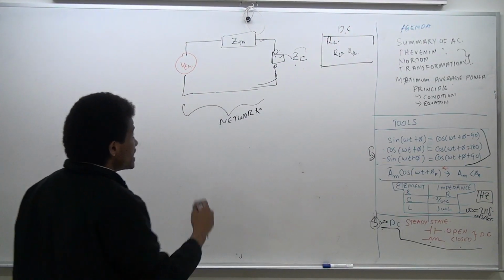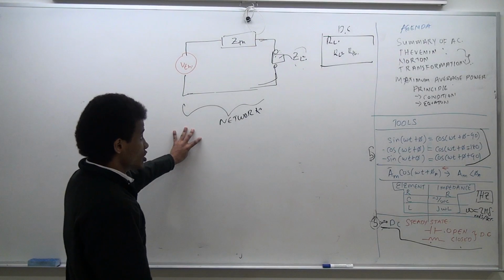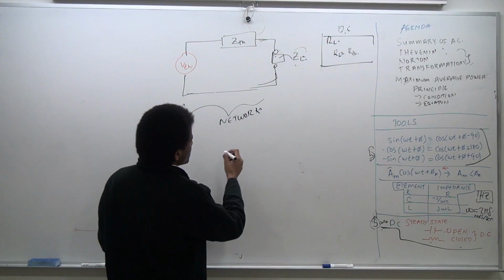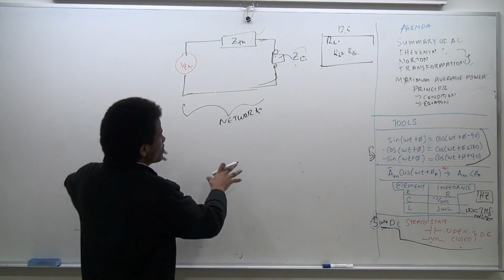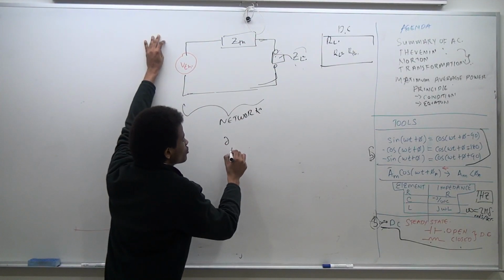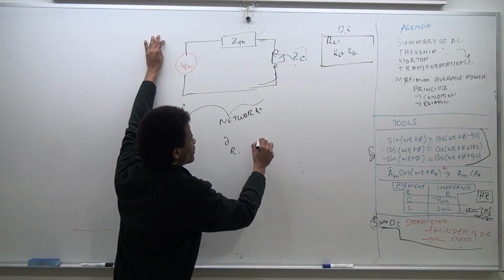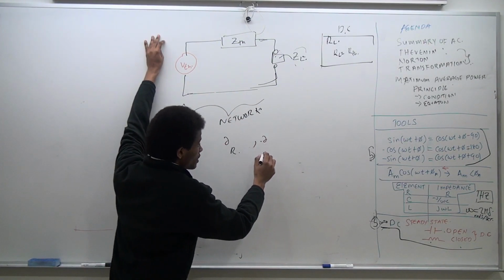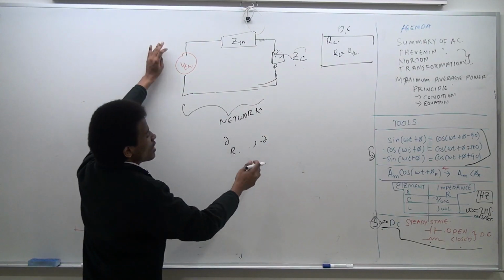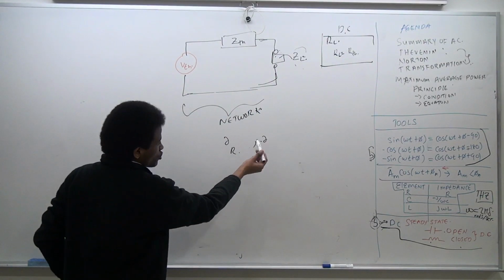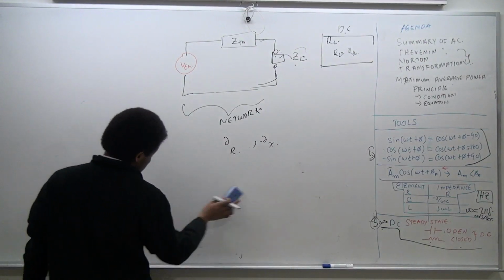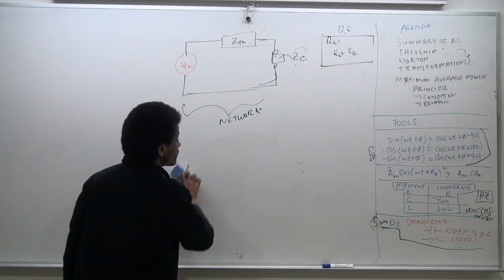But under AC, it becomes a two-dimensional optimization problem. We are now taking the derivative of the optimization function. It can be derived, it's very easy to do, but in the interest of saving time, we're not going to cover that. We're taking a derivative with respect to the resistance, and with respect to the reactance. Again, the reactance is the imaginary part of the load impedance. When we took the two-dimensional derivative with respect to resistance and reactance, I'm not going to go through the derivation, but we find out that indeed